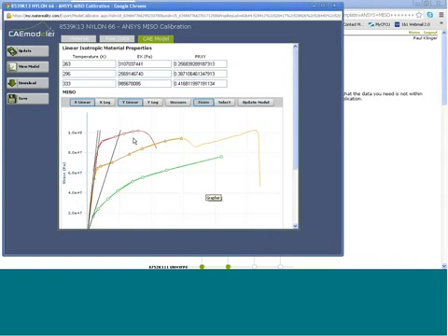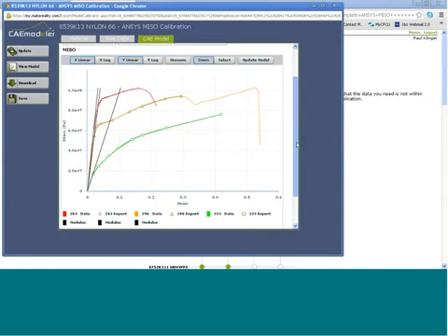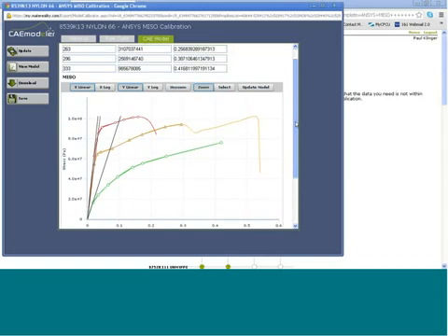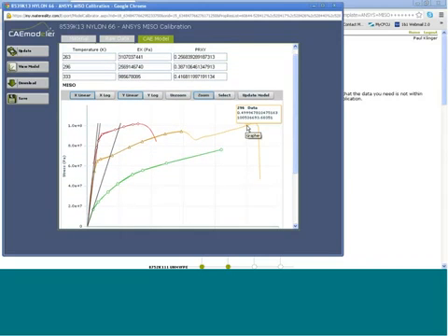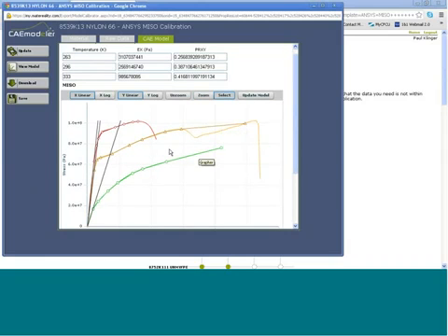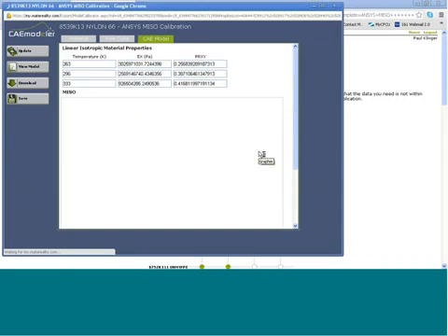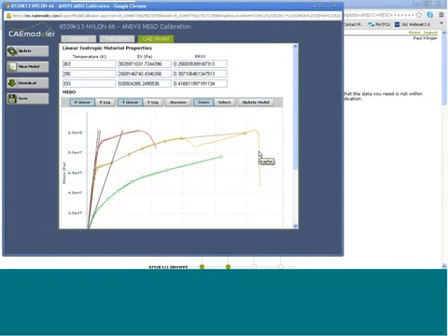This allows you to take a preview of the data, review all the contents. I can see the modulus. I could soften or stiffen the modulus if I wanted to. And I can even go in here and add and remove points. If I want to get rid of negative curves, for example, I can do that. Or if I want to remove certain data points, I can do that as well. And all I do is update the model, and it saves those changes.